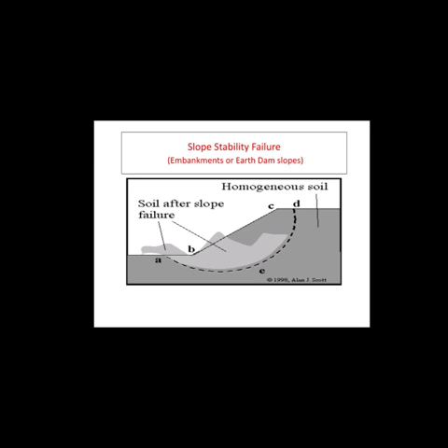The slope line ABCD fails under certain critical conditions such as sudden drawdown condition for upstream slopes of the earthen dam, or steady seepage condition for the downstream slope of the earthen dam, or just after construction case for both earth dams and